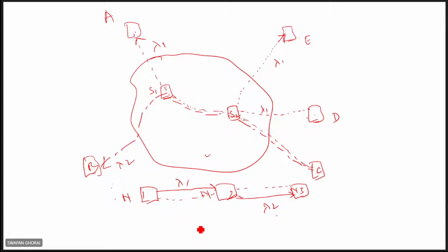So that is not there. So it's not possible. But in the same way, using wavelength conversion is possible. The same thing, I mean, blocking can be avoided. Say here the information carrying signal is lambda 2 and it is converted. Suppose lambda 1 is available here. If it is converted to lambda 1, and this is lambda 2, and if wavelength conversion is easier here, then you see information can be transferred from 1 to 3. So that is the wavelength conversion. Otherwise, blocking will result.